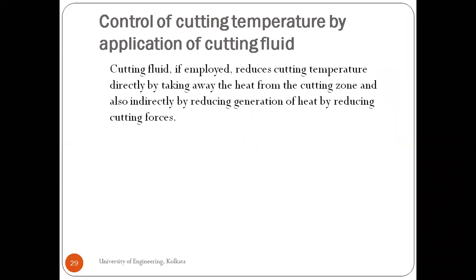Now next is the control of the cutting temperature by application of the cutting fluid. If cutting fluid is applied directly, there are normally three functions of the cutting fluid. First, it reduces the cutting temperature.